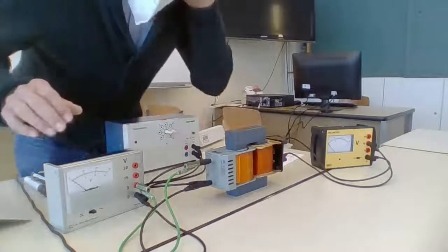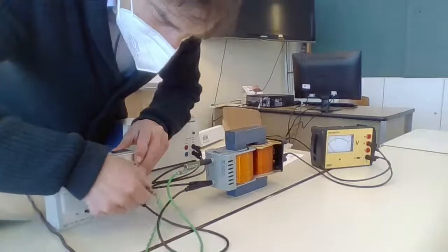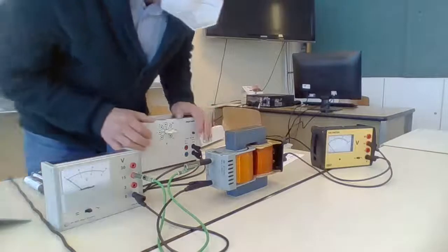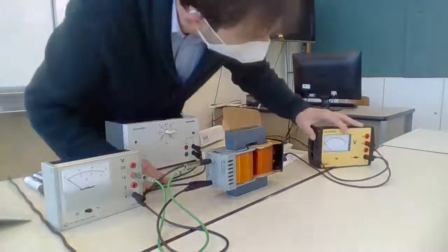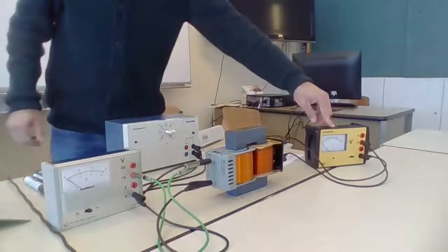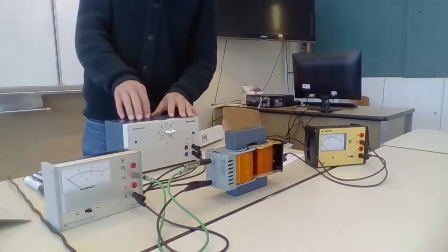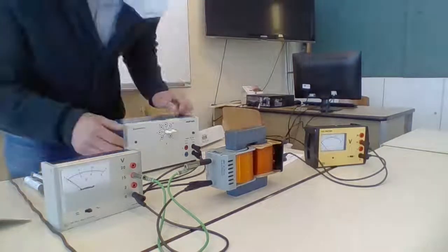Okay, so I'm going to send in 12. So I got to move my voltmeter so it can handle 12. Now it's set for 5, 10, 15. Hopefully 12 coming in, 3 to 1. How much should I expect on the other side? I'm sending in 12. What should I expect on the other side? 4 volts. Here we go.